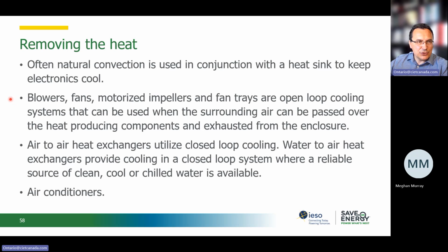We can use forced air flows, blowers, fans, that can actually increase the heat transfer function. We see air-to-air heat exchangers so that we can have a closed loop for the cooling.